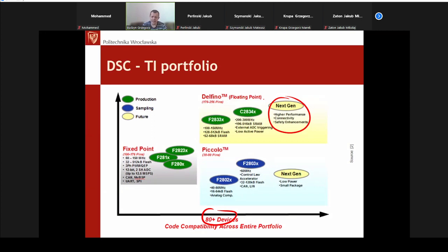Still, what is excellent here is that the core itself has a lot of features coming from the DSP world. Texas Instruments has always been an expert in signal processing, and for example, in those cores we've got a lot of addressing modes coming directly from the DSP world. There is no support for butterfly addressing or for circular buffer addressing. Okay, that's true. But there is support for fast data transfer, for example, fast data access through different memories. So, many interesting features here as well.